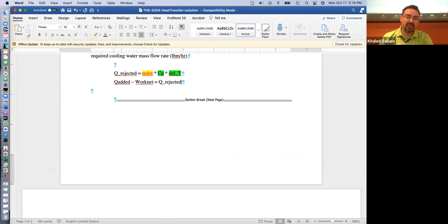So someone was actually asking why are we given the m dot water that's going into the cycle? Because this Q added is m dot delta h plus another m dot of the reheat times delta h. Right? This is Q added. Questions?